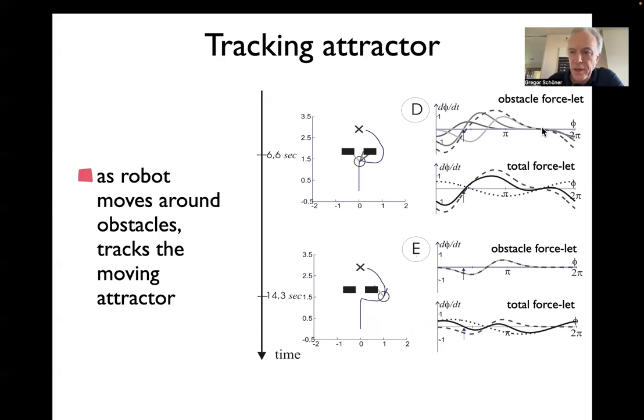They're close enough for those to overlap this way. And then there is an attractor sort of on the back of these obstacles, while the attractor toward the target here makes this negative slope. And here it's overturned. The sum still has a repeller in this direction. And that's how this makes actually that the vehicle is currently turning, and we'll see in a moment the time course of that, toward the attractor that's here on the back. There's actually a broad range where it could be moving in the back direction.